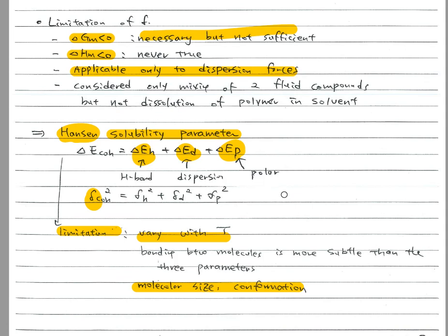So we have learned about polymer solubility, and how we can determine which solvent dissolves which polymer. Basically, you need to understand the basic principle. Thermodynamically, what determines the feasibility of the polymer dissolving in a solvent is the solubility parameter delta, the Hildebrand value.